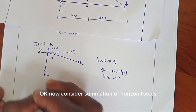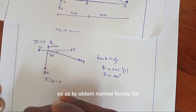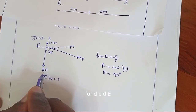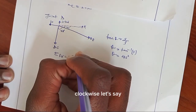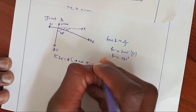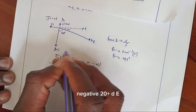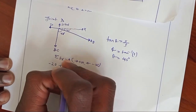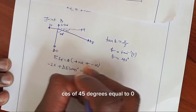Okay. Now consider summation of horizontal forces so as to obtain normal forces for DC, DE. Summation of horizontal forces, right side positive, left negative. Negative 20 plus DE cos of 45 degrees equal to 0.